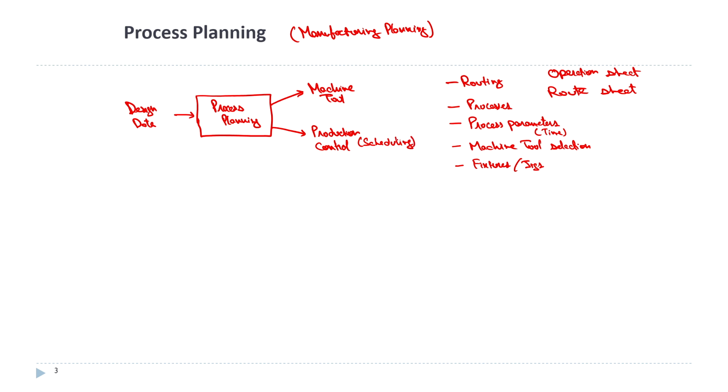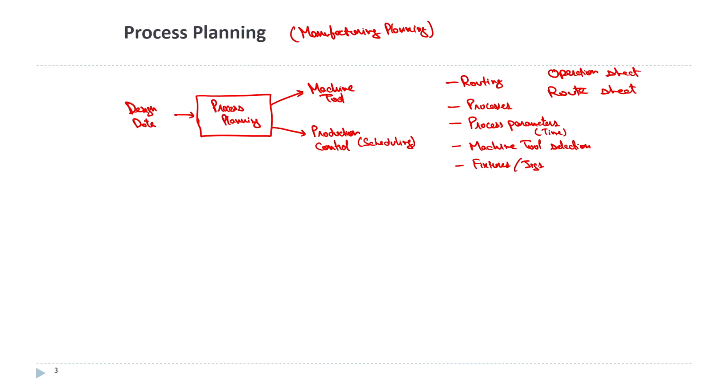To put it in a nutshell, I would say the aim of the process planning is to identify appropriate supplementary information from the drawing to aid the processes. That is, to have the dimensional information and the geometric information from the drawing or the design, and try to communicate it to the machine tool and try to have the final output out of it. So, process planning helps us to communicate things to the machine tool.